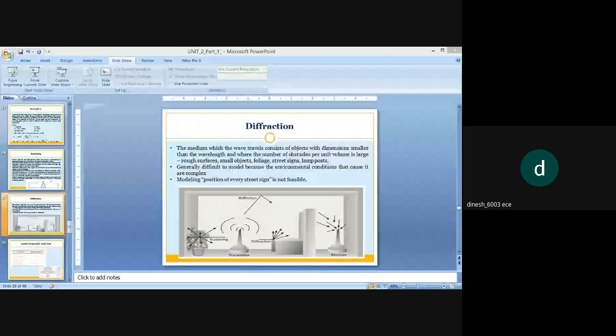So now we are going to find the propagation range with respect to the environment. In retail stores, the path loss exponent should be 3. In factories, 1.6. In large storage areas, it should be 2.2 as the design factor.